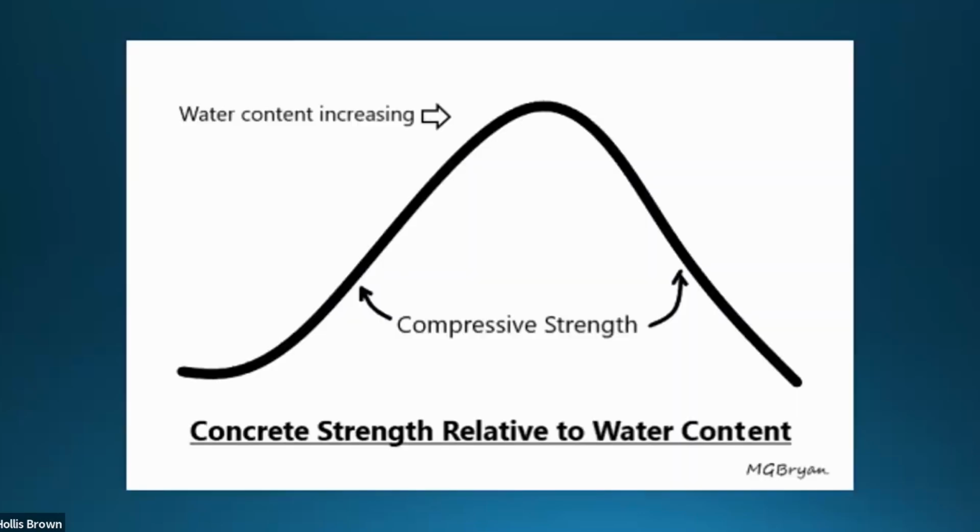And this kind of leads us into the slump test, but you want your concrete, when you're mixing it, as dry as possible. In fact, the Romans were actually ramming the concrete into forms. They'd have it very dry and tamp it in. The more water, the weaker the concrete. That's what the slump test is trying to determine, how strong the concrete is, and it's all based on water.